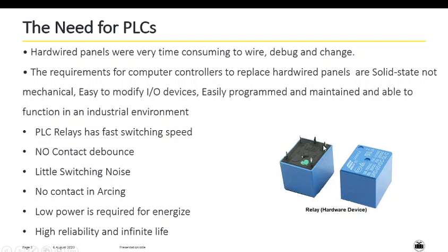This is normally open, and this is the common terminal. We will connect the line, or the red wire, to this supply, and we will get this voltage at this point, because it is normally closed. Whenever a signal is not applied, the signal will be available over here.